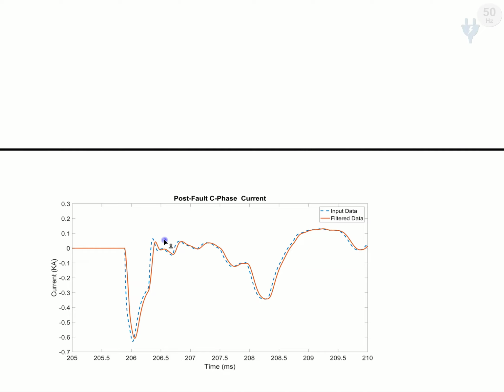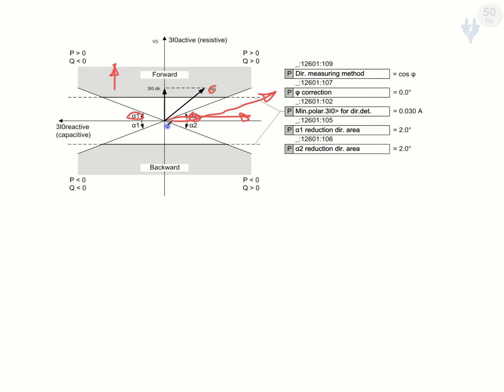If it is like this and we don't give any time delay for the direction determination, in the initial time it will misguide our system because the current will flow in the reverse, and the relay will be misguided that the fault is beyond, meaning reverse. Actually, the fault is not in the reverse direction, but our relay will be misguided. At the initial time, that current is in the reverse, backward direction. So the system will introduce it as a reverse fault.